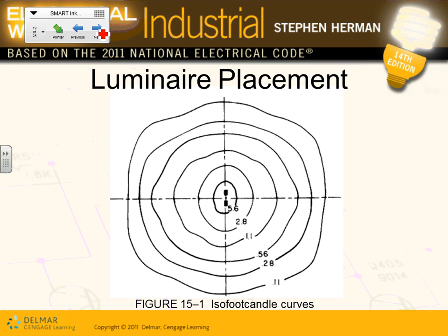Okay, the rest of it, guys, is when you put isofootcandle curves. Remember the isofootcandle curves? When you put a picture like this, these lines represent the footcandles in this area. So, for example, and I'm telling you something that you guys know, all these points are represented by 2.8. All these points are represented by what? On this curve, 1.1 all the way into 11. Am I reading it right here? No, 0.11. Okay, this is a point.